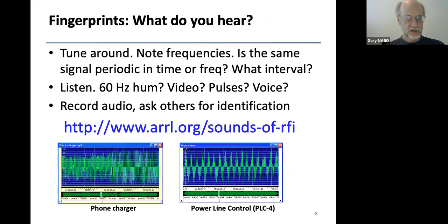So, fingerprints. The first thing is, I have noise. Well, tell me about it. What do you hear? So you tune around. What frequencies is it on? Is it every 50 kilohertz? Which bands is it on? Is the signal periodic? In time, does it pulse or something like that? What times of day or night is it on? Is it on just for a while? Is it on repeatedly? Things like that.